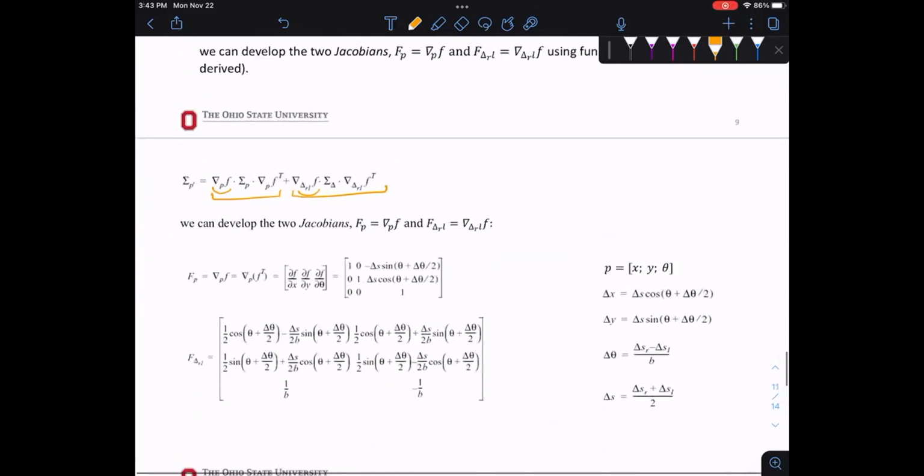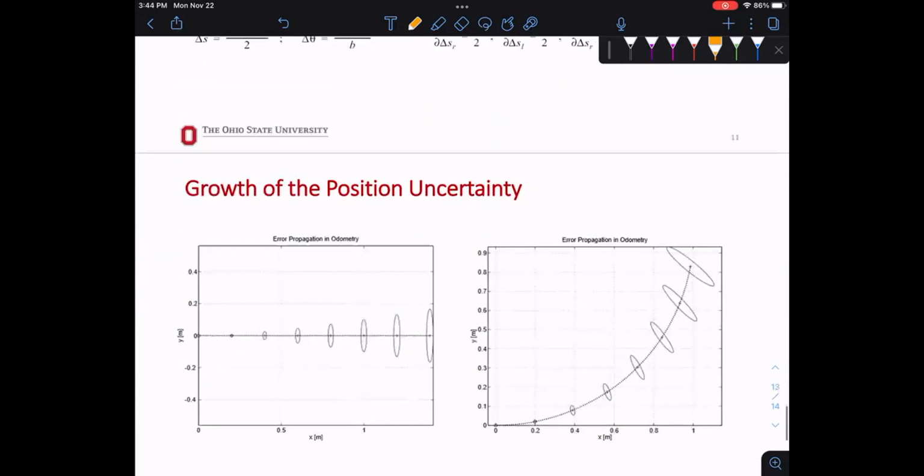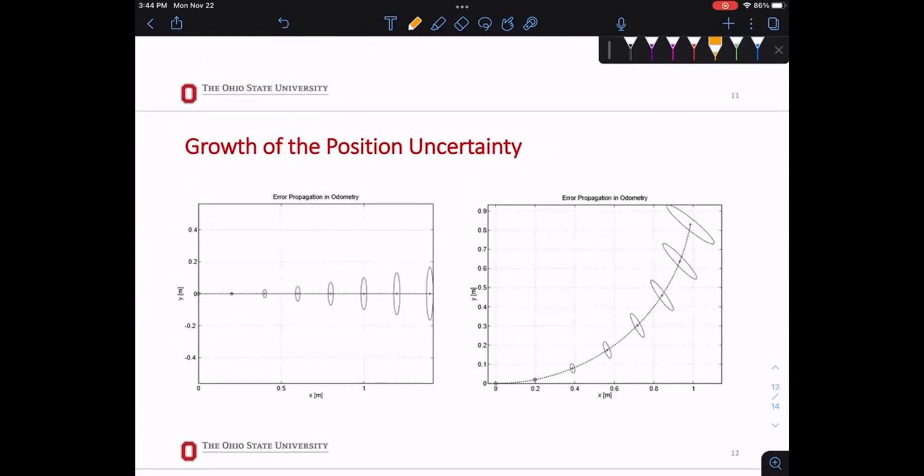then we can plot the position, because our position is the current position plus all of these errors that you will put here, right? So current position plus this estimation because of the motion, plus this estimation because of the slippage, and it will give you the actual motion path traveled. So if you plot that, you will get something like this. If you want to show the error propagation by an ellipse, you can find how to do that using the source I gave you.